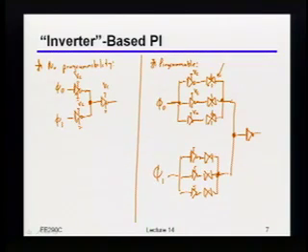So as Ida was saying, we want to keep the total width fixed. In other words, if there was a total width here of 10 microns, you'd program it so that whenever this was 5 microns, this would be 5. If this was 2, this would be 8. If this was 1, this would be 9, and so on and so forth. So you're conceptually just moving width from one input to the other. By the way, there are many other ways you can do something similar, but this is the basic idea. Does that make sense to people?